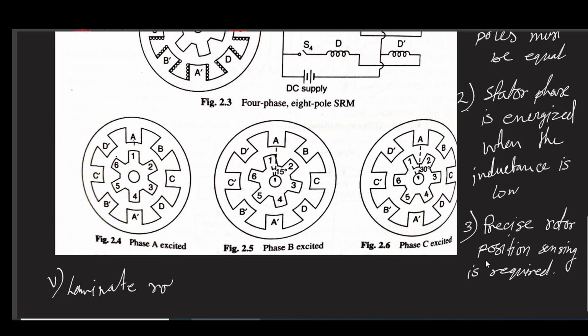Here, the point is very important because if you do not do it, due to eddy current, meaning high value of eddy current, this lamination cannot prevent your hysteresis, but lamination will surely prevent your eddy current. And when this eddy current will not be present in a considerable amount, then the heating of that iron part due to eddy current will be reduced by a considerable amount, and that reduction will help you to ensure better